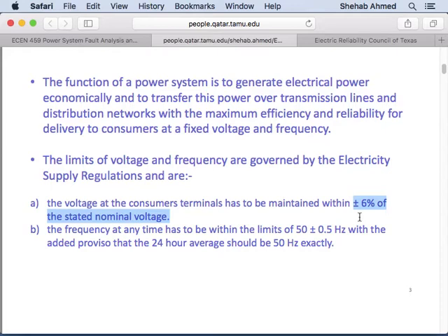So do you think they will accept a higher power loss? Probably not. So they designed this within certain limits, right? Every piece of equipment is designed to have operating limits of voltage. After that, it will disconnect or not operate properly, or you will burn it down. If it doesn't have the proper protection, it will probably burn down. If it's protected properly, then it will disconnect itself. It will say, I cannot operate now, the voltage is too low, right?